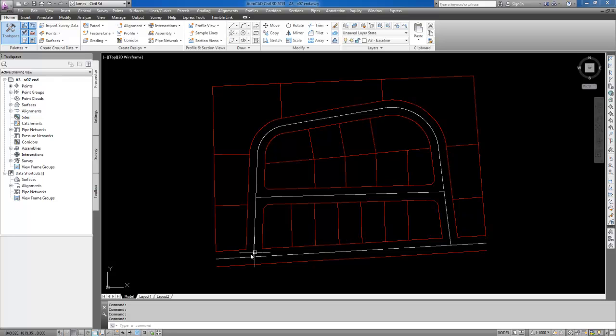The next step is to turn these line segments, if they are line segments, into polylines. To do that, we go up to Modify, Polyline Edit, and simply select the line segment. If it is not a polyline, AutoCAD will ask, object selected is not a polyline, do you want to turn it into one? You simply say yes, you can hit enter here, and it will turn that object into a polyline. Now, this is for Faraday.